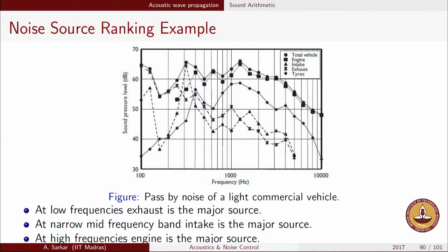You can observe a distinct peak possibly in the third vertical line. But again, on the high frequency side, it is the engine noise which dominantly latches on to the total vehicle noise. So on the high frequency side, if you want to get any benefits, then one has to look for major refinements in the engine structure and try to bring down the engine noise. If engine noise is brought down in the high frequency region, then the total vehicle noise at high frequency will also be controlled.